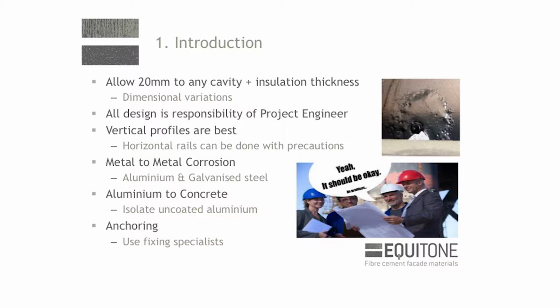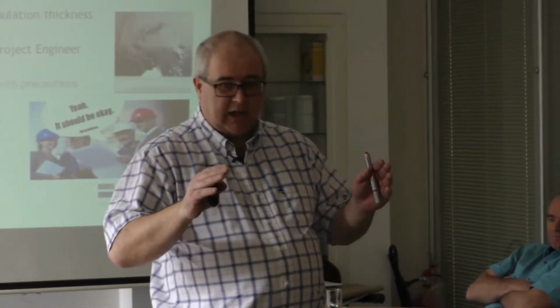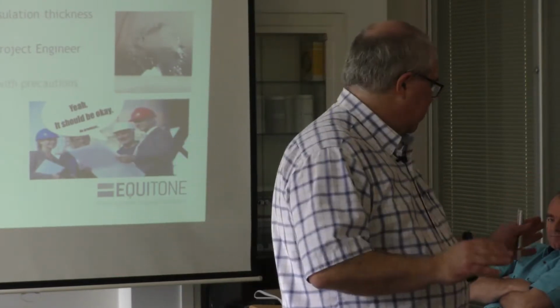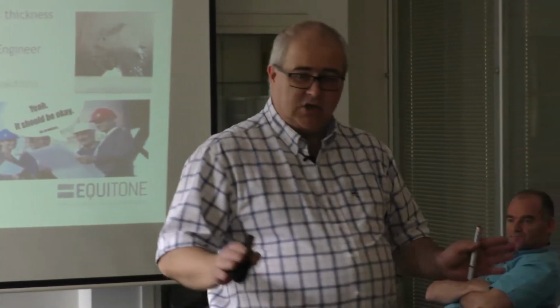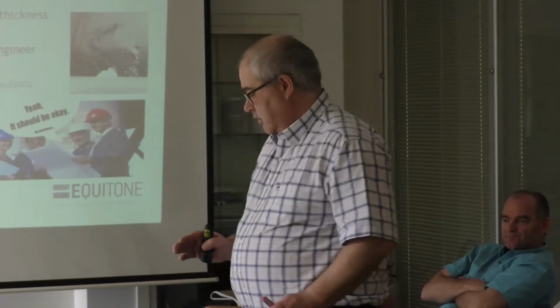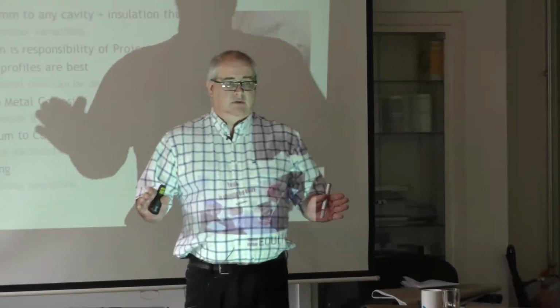Vertical systems are best. We can do horizontal systems, but there's some extra work in it and bigger cavities. Now, for you guys, the installer guys down the back, be very careful, metal to metal corrosion. You guys will probably specify it, or the guys will specify you use aluminium with aluminium, you can use stainless steel with galvanized steel.